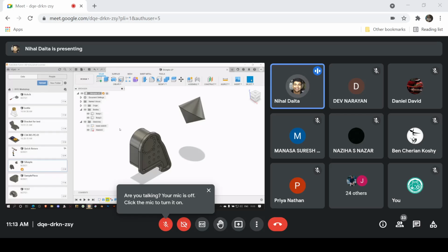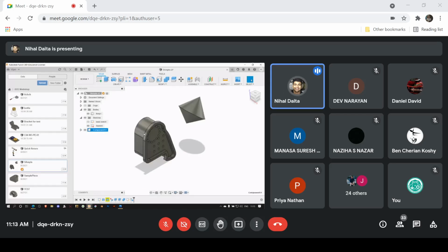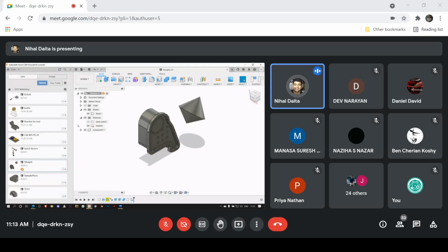As you can imagine, these are just individual parts. So if you're trying to couple more than a single part, you have to use another form called components. The basic thing is you just click on the body, and there is this button right here, assemble this new component. You just click type standard from bodies and select a body and OK. And as you can see here, there's a new thing that has popped up, and this can be moved by simply dragging the mouse. So this is a different type of mesh, not really a different type, just a different name, so as to differentiate between these two. Only these component parts can be assembled. So I'll just leave it at that.